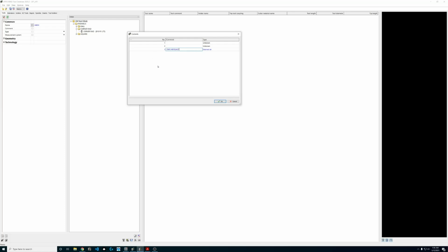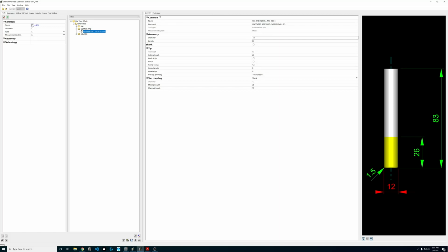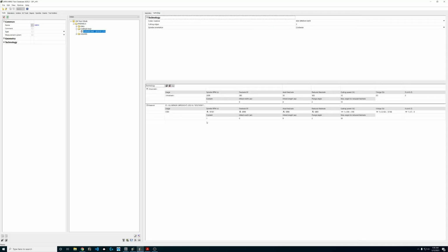And then again, in your post, you'd say, okay, let's see if I can get this right. So for us, external air blast on a Siemens, on a DMG would be M8 for external usage, and M72, I believe, is the air blast master. And M7 and M72 would be for internal air. So back to technology, so we can define our coolant there.